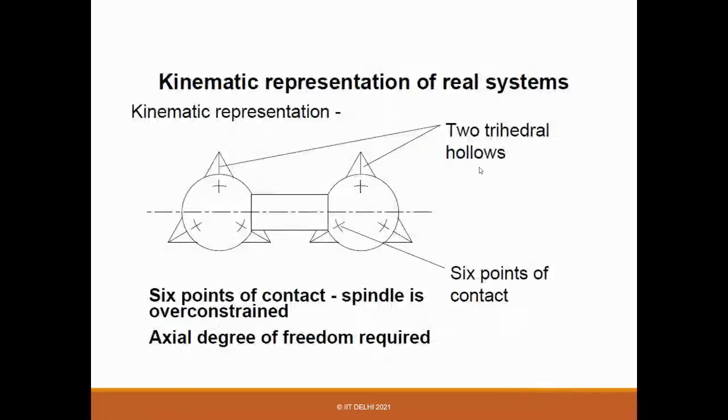Many times I also ask, if you see certain designs, certain concepts, can you find a kinematic representation? What is the basis model? And how to analyze it? Because unless you are able to convert it into point and flat contacts, only then will you be able to see what the over constraints are, what the issues are in that